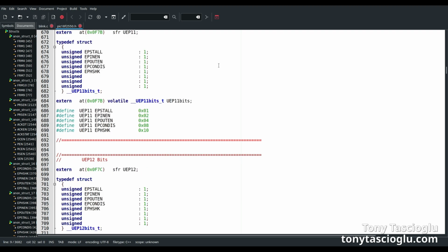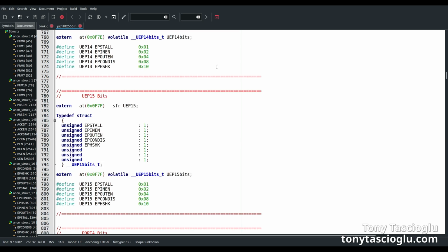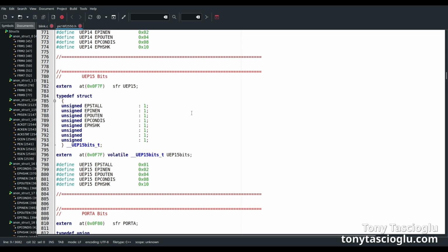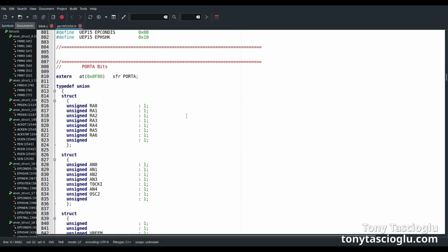So because these are memory mapped I/O, what you actually need to do is place a 1 or a 0 in a particular bit of the RAM, which will happen to trigger the digital pin. But when you write pin 10, your program needs a way of figuring out which memory address that actually is in, and that is located in this header file.